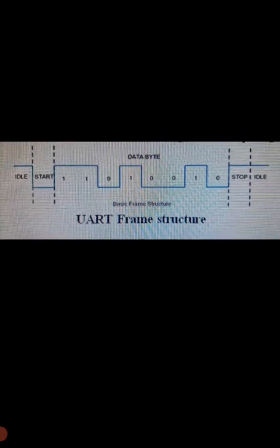The LPC2148 has 2 inbuilt UARTs available, UART0 and UART1. So we can connect 2 UART-enabled devices, such as a GSM module, GPS module or Bluetooth module, with the LPC2148 at a time. UART0 and UART1 are identical, other than the fact that UART1 has the modem interface included.